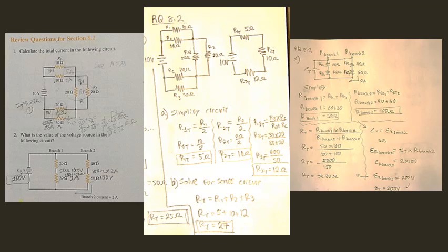So the voltage drop at branch 2, we know if we find out our voltage drop at branch 2, since that's where we have our amperage, that would be the same as our voltage source, since voltage is equal in all branches, is equal to the source in all branches of a parallel circuit. We know that by using the known laws, Kirchhoff's law.